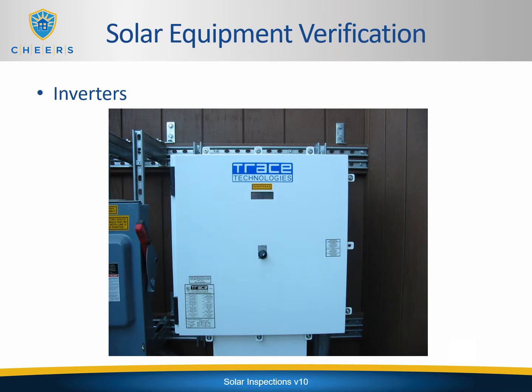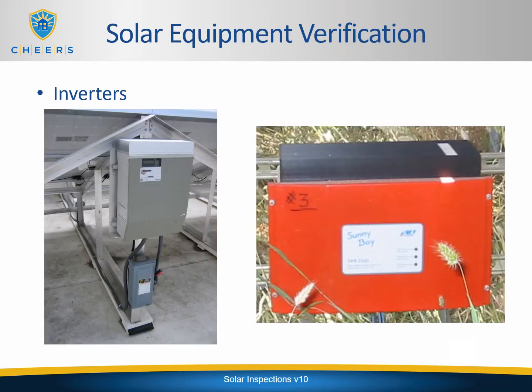Every inverter will have a location where you will find the make and model number. For this example here, in the lower left-hand corner, you will see a label that lists the make and model number as well as a lot of other information. These two examples, again, there is a label that's clearly located on the inverter that will give the make and model number for your verification process.